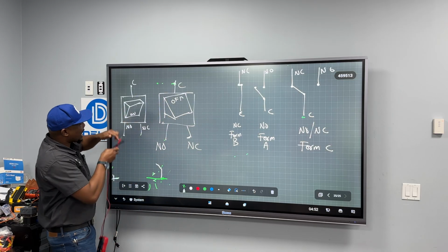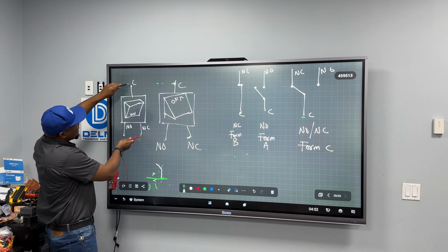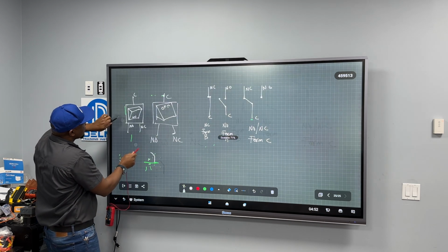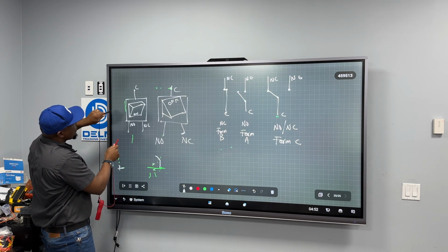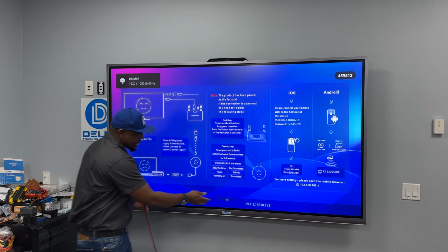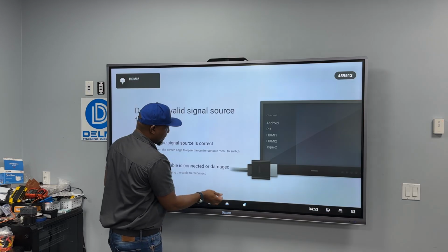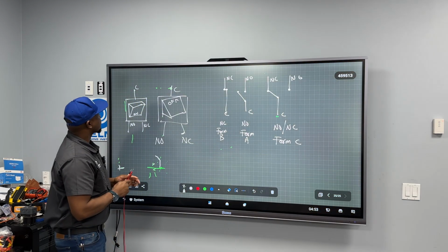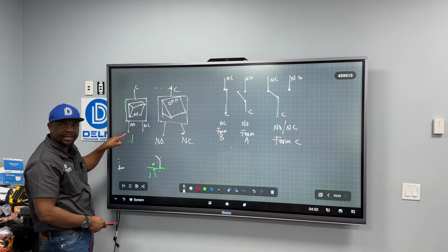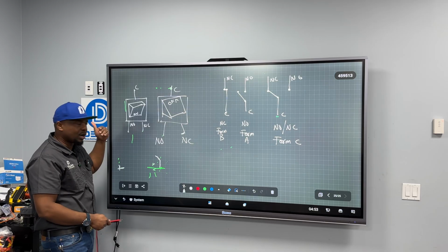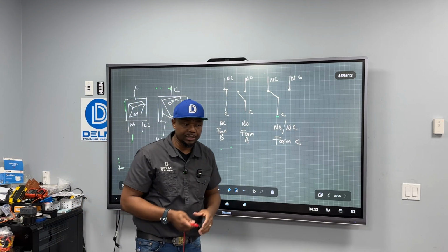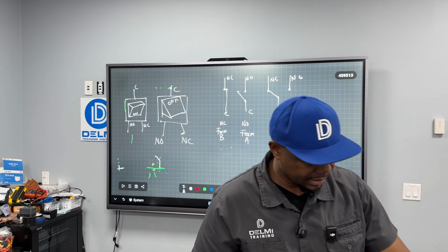However, when I push this down and I'm holding onto it, and I get a beep from here, then it's just going to tell me, so long as my finger remains on this button, I'm getting a continuous beep. But the moment I take my finger off, the beep goes away, then it tells me it's a momentary type of switch. So let's demonstrate it here.